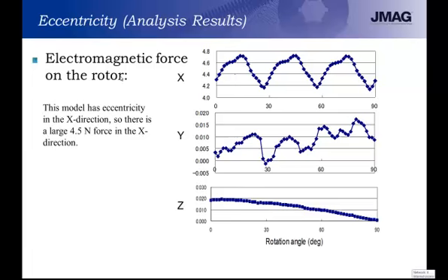Now, if we look at the results of this analysis, we can see that the electromagnetic force on the rotor is relatively high in the x-axis and the y-axis. So that would result in an eccentricity, which could then lead to noise and vibration in the machine.